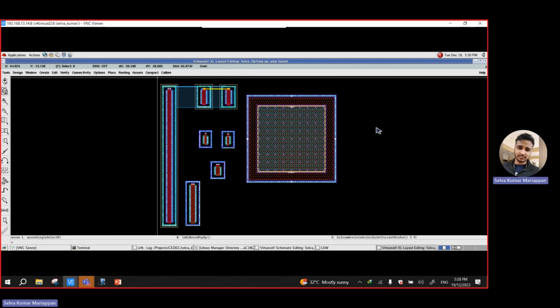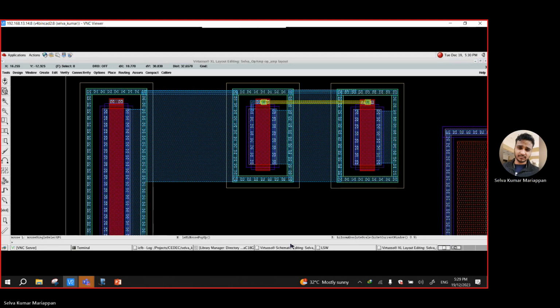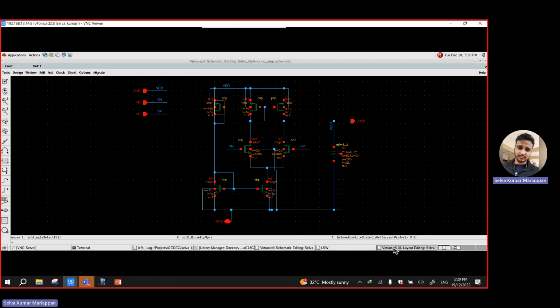See, so now all my VDD and bulk is connected. All the source and this one are connected. So now the next one I have to connect is, okay, so all these are settled, this is settled for this transistor. So I have gate to drain as well. Okay, then I want to check it here.